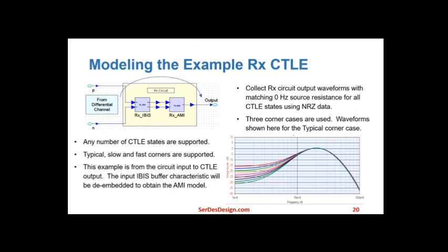For modeling the CTLE, collect the Rx circuit output waveforms and matching 0 hertz source resistance for all CTLE states using NRZ data. The waveforms shown here are from the typical corner case.